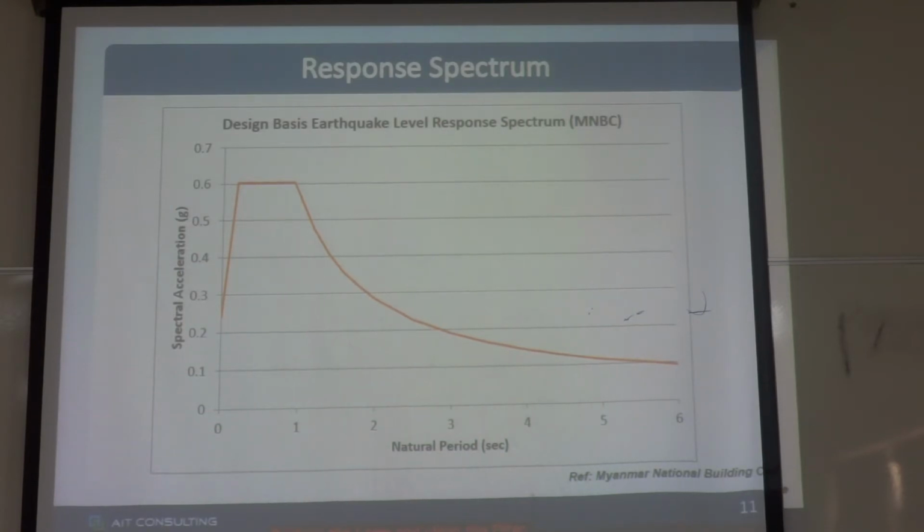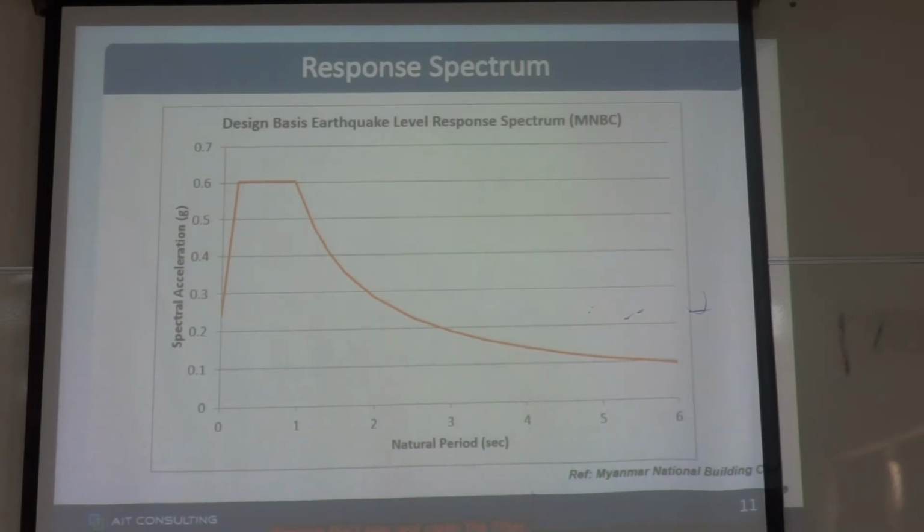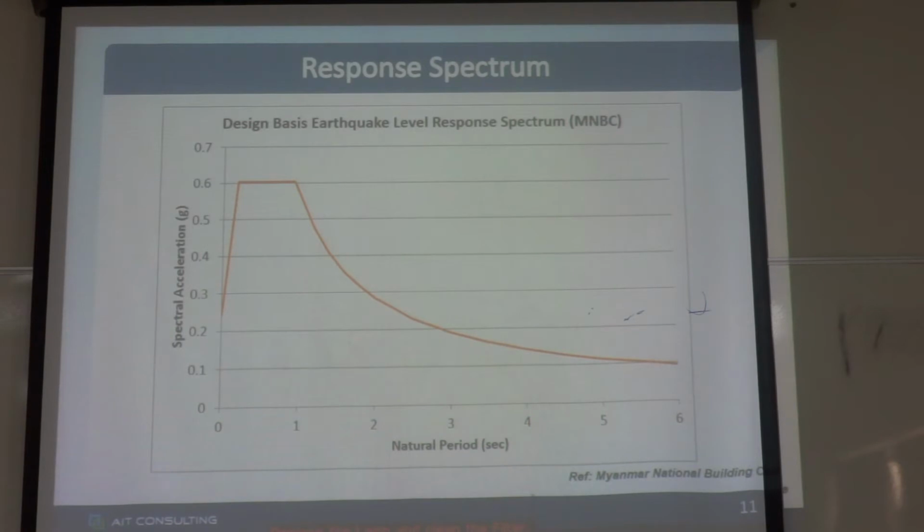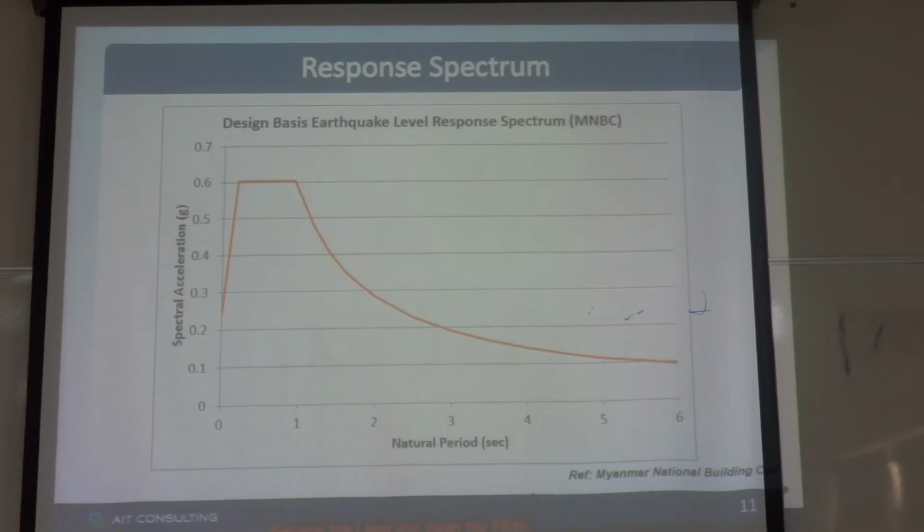But when you design for wind, it is reverse. If your building is too flexible, the wind force will increase. There is a factor in wind loading, so we have to take care of that when you design tall buildings.